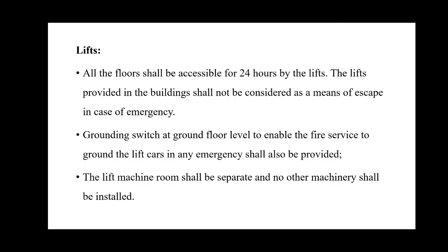Next, lifts. All the floors shall be accessible for 24 hours by the lifts. The lift provided in the building shall not be considered as a means of escape in case of emergency, as discussed earlier. Grounding switch at the ground floor level to enable the fire service to ground the lift cars in an emergency shall also be provided. The lift machine shall be separate and no other machinery shall be installed in the machine room.